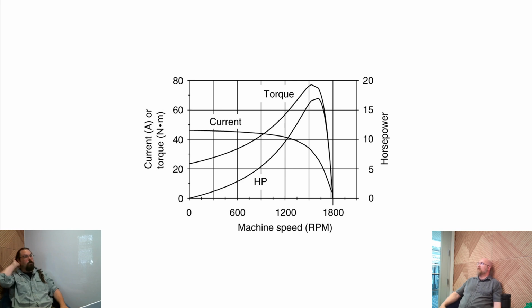Like, how is torque suddenly peaking at nearly our rated RPM? That doesn't make any sense. Yeah, and it just has to do with, pardon my French, the fact that when we're dealing with this rotational magnetic field, it's got to come up to speed.